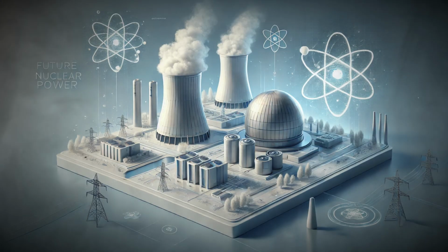Their smaller size allows for greater flexibility in deployment, whether to power remote communities, industrial facilities, or to complement renewable energy sources. SMRs also incorporate advanced safety features, often relying on passive cooling systems that function without human intervention or external power. Another area of development is advanced reactor concepts, including fast breeder reactors and molten salt reactors.